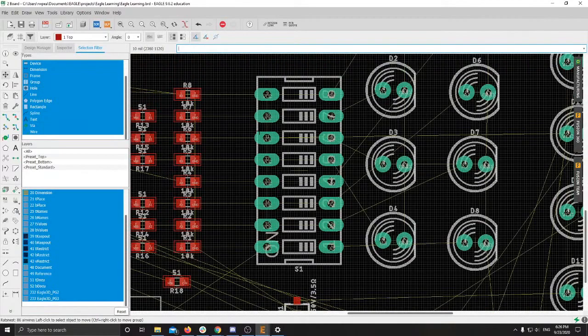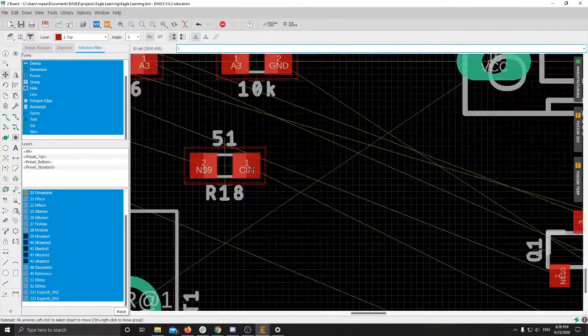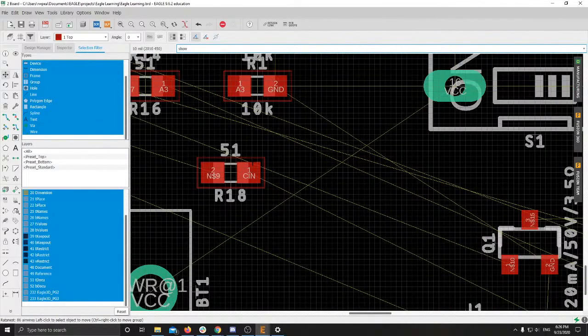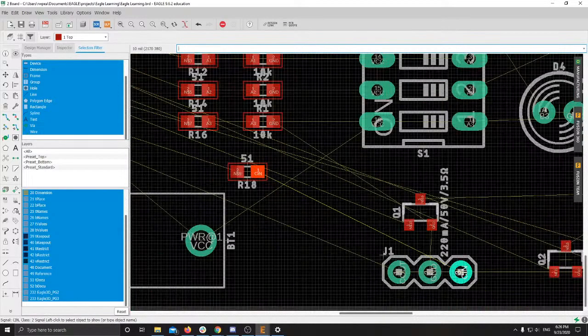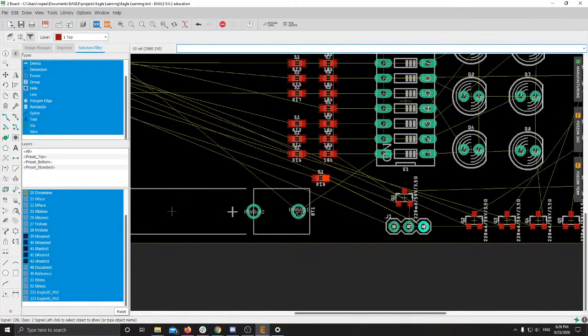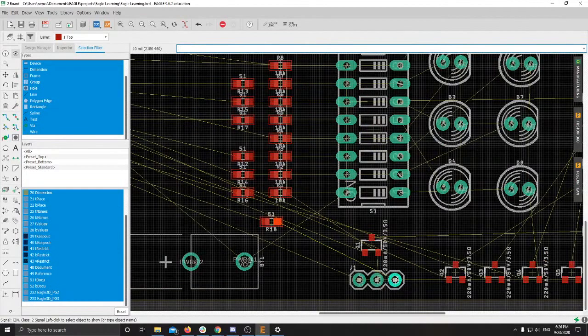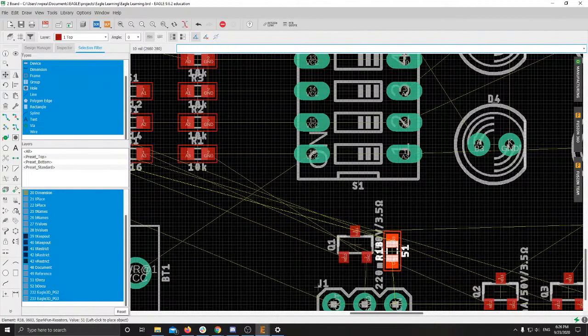So one useful thing I can do is say, oh, this needs to be connected to the C in trace. It can connect here, but I want to see if maybe there's somewhere better to put it. So I can type show and then the name of the net. So show C in. And it should highlight everything. You can see this and this are highlighted with that name. I can see, okay, that really is the only one like that. So it can be put... If I go to the move tool, right here.